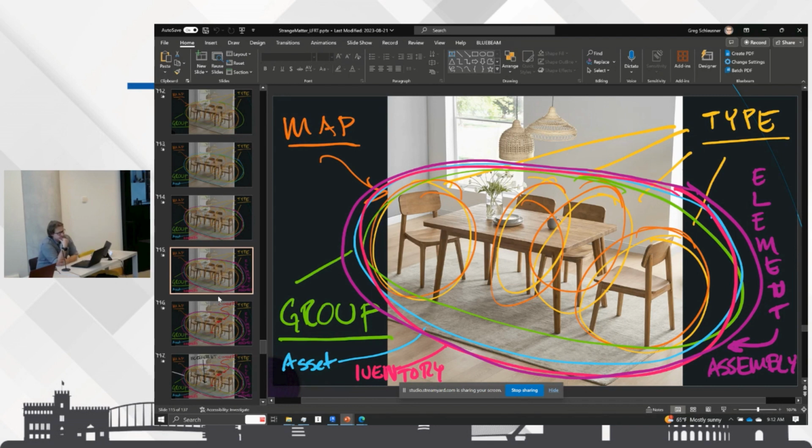So I have two ways of doing it. Let's say you have a bridge, and the surveyor goes and scans or measures the bridge with the total station. You could take those points and represent them as IFC annotation and create a separate IFC file, which is only the points, and that's the as-built information. Or does the as-built information stay in the property set?